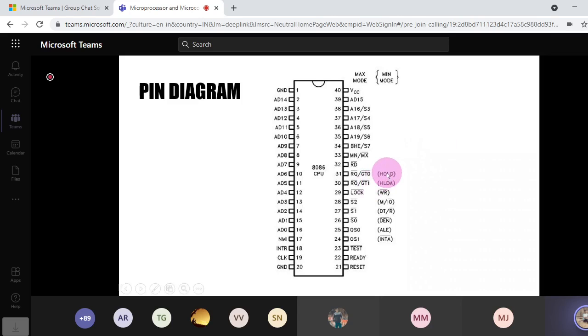Here we have got these minimum mode operation pins, and it has one ALE here, right? And from this pin to this pin again, it will be interpreted as these signals in the maximum mode. So in maximum mode, this ALE pin is missing because ALE pin that you see here, it was available in minimum mode, but in the maximum mode, that pin was missing.